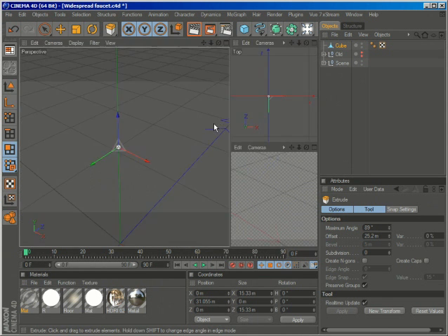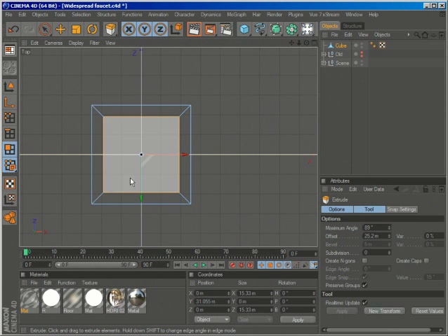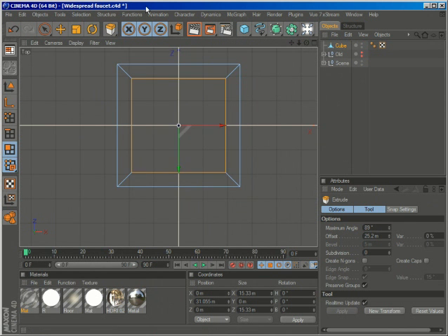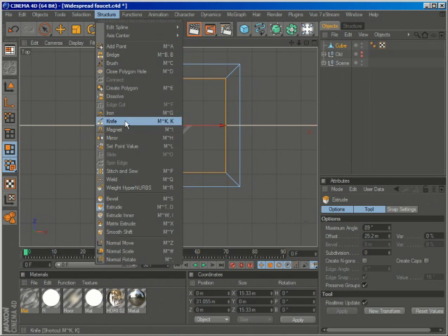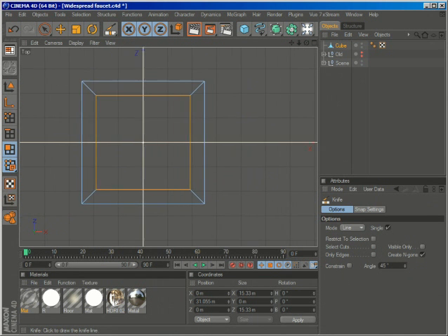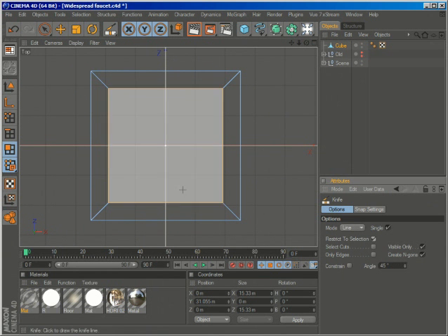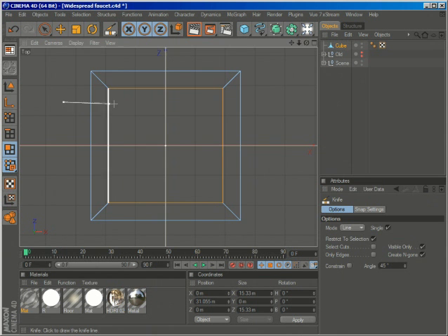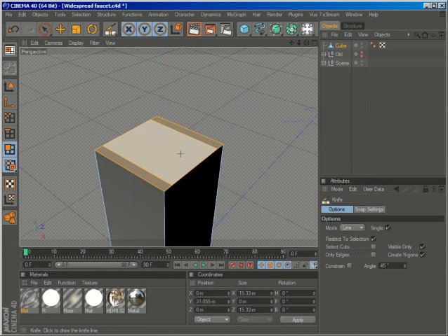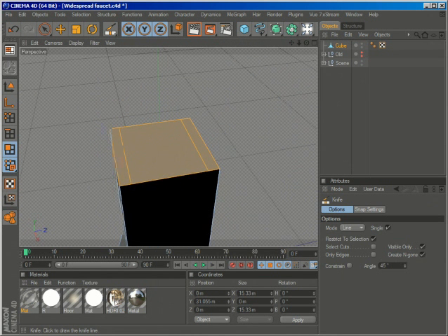And I will now make some cuts. So I'll get to the top view and use the knife. That would be in structure knife, or K on the keyboard for a shortcut. I'll select visible only and restrict to selection, and just making one click, holding shift and dragging, just to create 3 sections on this polygon. It doesn't have to be perfect.